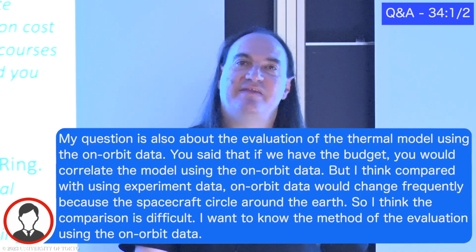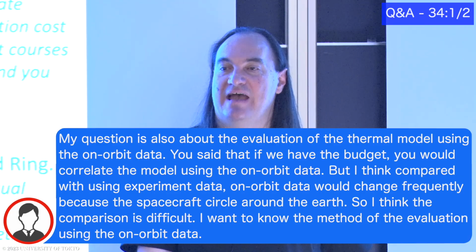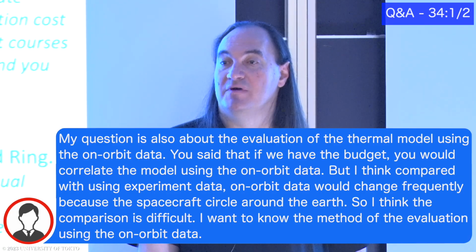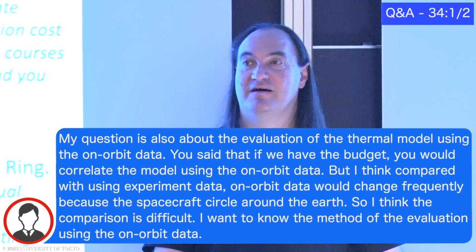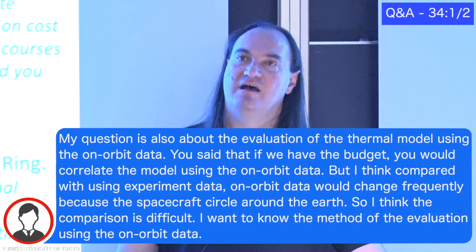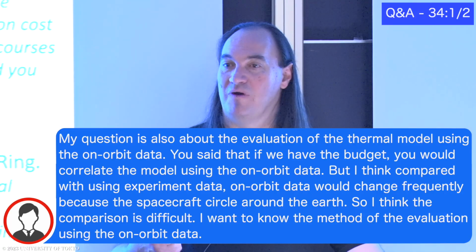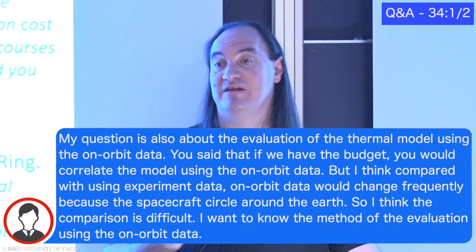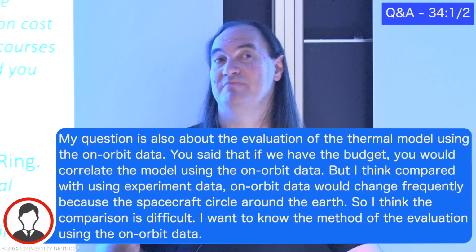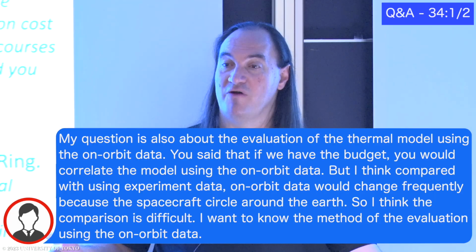So in that case, it's really gathering as much knowledge as you can about the system. So if I'm having to correlate to a flight around the Earth, I need to know, well, what's the beta angle? What time of year are we? Do we have any data for what the solar activity is doing? Do we have any knowledge of the Earth IR at that point? What's the transient power profile going on?